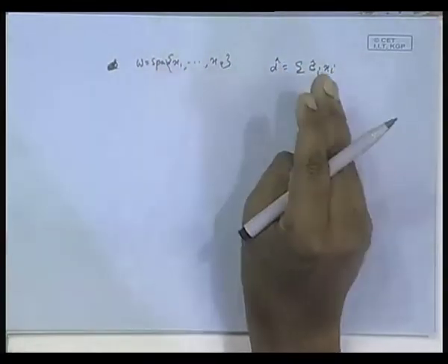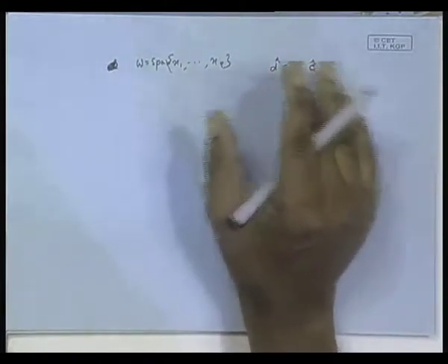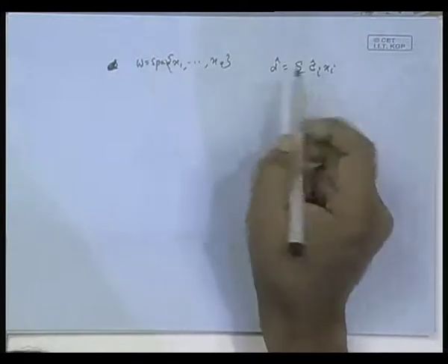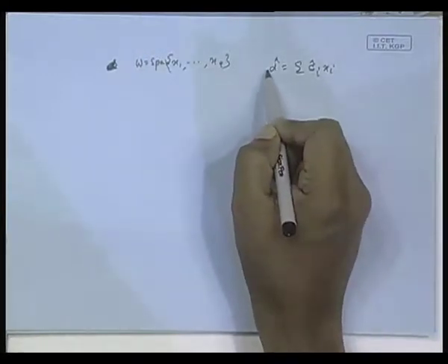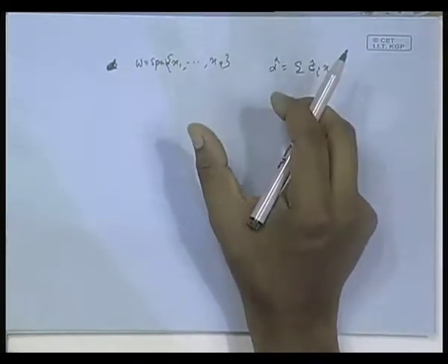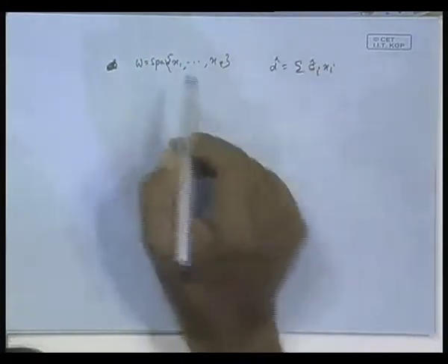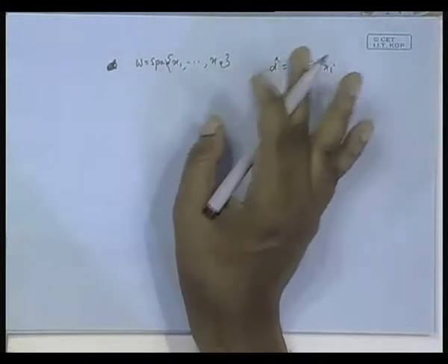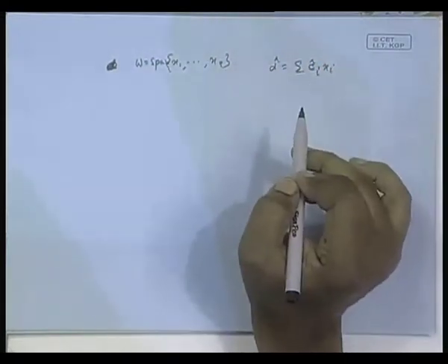Here in this space, the vector space of random variables, the inner product was the correlation between random variables, norm was the variance, norm square was the variance and all that. So, if you take the difference between D and D cap, that error will have minimum variance, and that error will be orthogonal with each of these x1 to xq, that is the correlation will be 0 and all that. Okay. That is what we found, that will give you the optimum coefficients.